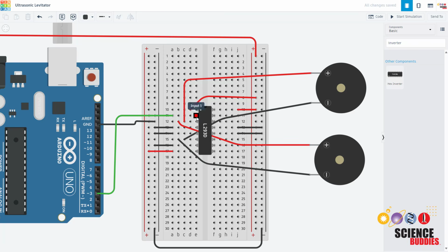We have one more trick up our sleeves to get more output out of our transmitters. You may have noticed earlier that only one of the H-bridge inputs is connected to an Arduino pin, and the other one is just grounded, meaning this input is always going to be low or 0 volts. And we are never going to switch the polarity across our transmitters. So this pin alternates between high and low. So for example, there will be a positive 12 volts applied to the transmitter, but it never reverses. If, for example, I set this pin low to 0 volts and this pin high to 12 volts, then there would be 12 volts applied in the other direction, giving me a total of 24 volts of amplitude across the transmitter, in theory resulting in more power output.